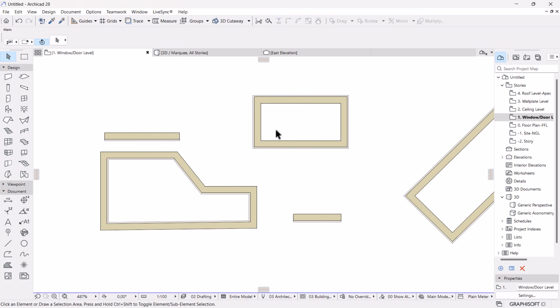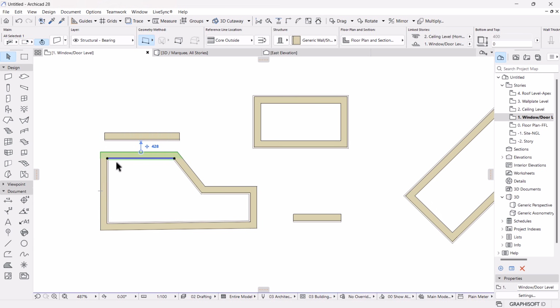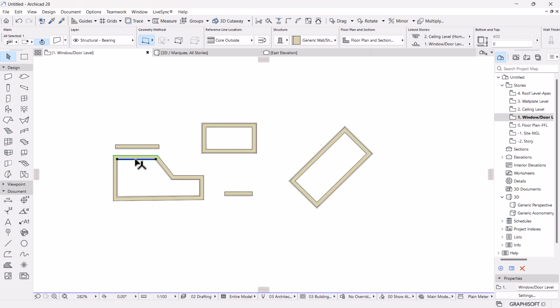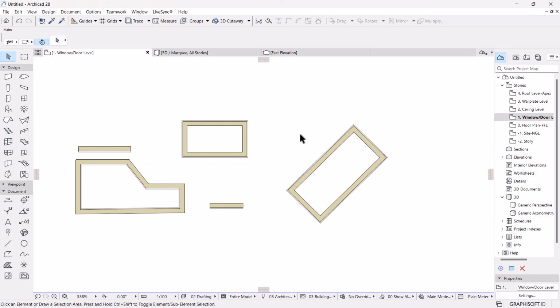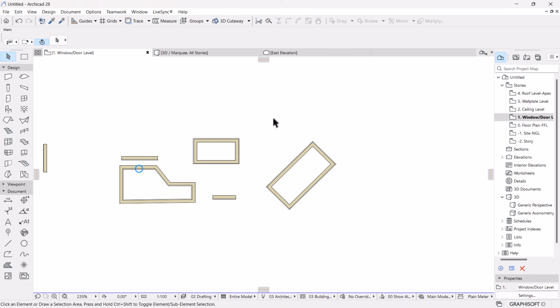differ. As you can see here, in this case, we have the finish of our wall on the outside. Here we have it on the inside. Why? Because if we drew this one with the reference line inside, and then went to the right, placing this clockwise. So these are little nuances in placement and reference line location in ArchiCAD.